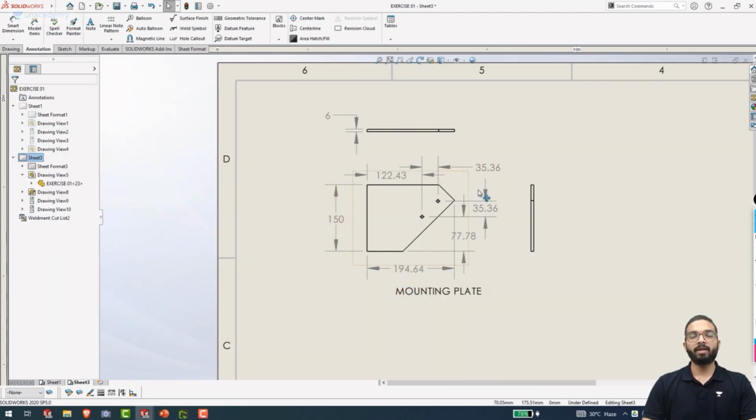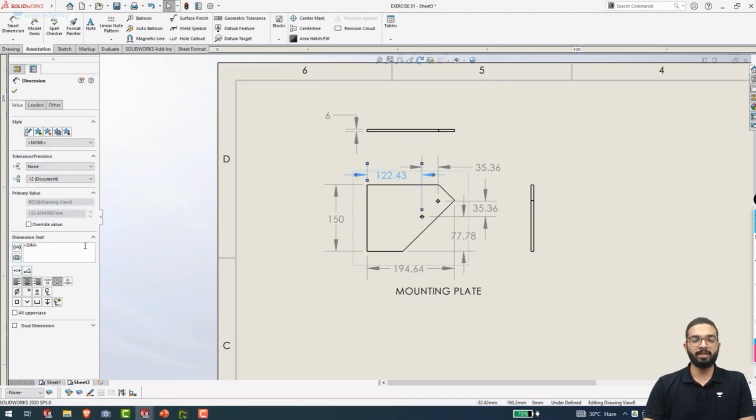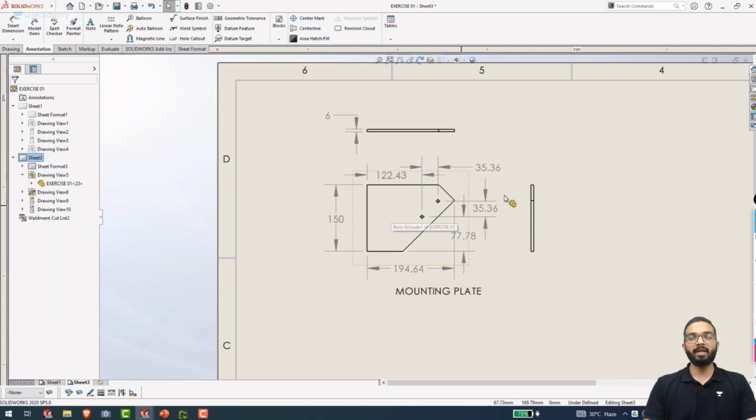Here you can see that we have some values over here which are in decimals. Basically it is not possible to achieve this accuracy. So in Solidworks we have an option to round this off. I will select this value, go to this precision over here that says round off. From here you can see here that some dimensions over here are in decimals and it is practically not possible to create or replicate these dimensions while manufacturing.